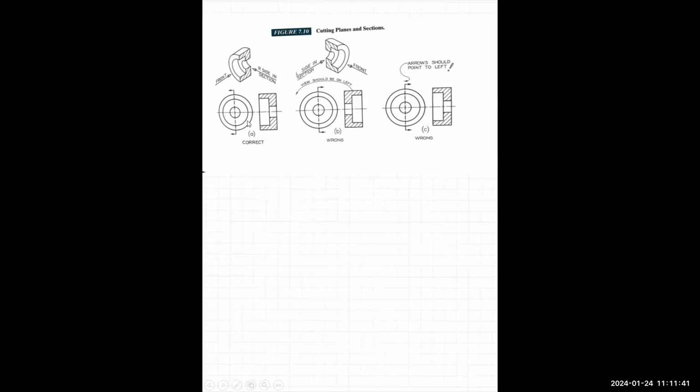Slice the object, draw the section. Slice the object, draw the section. The arrows refer to the view side, which side you're looking at, this side. That's what that is. Same with this, looking at this side over here, that's what that is, right? They pointed them the wrong way. That's the wrong one, showing you not good, not good, good. So it can get confusing as far as like, which side do I draw? So just be careful. Whichever way you put your arrows in is the view. That's the side you're looking at.